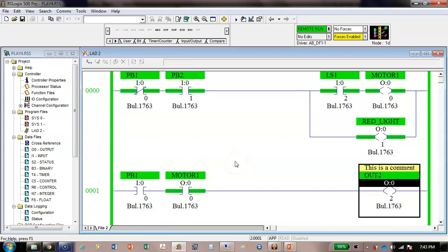So any questions? We're going to go back and actually look at the rules now that I followed, but even though I followed the rules, I still had a problem. My problem was, here I'm using normally open, here I'm using normally closed. When I open up this one, then this relay drops out, which means this opens. So this output right here never becomes true. But it's in the right syntax.